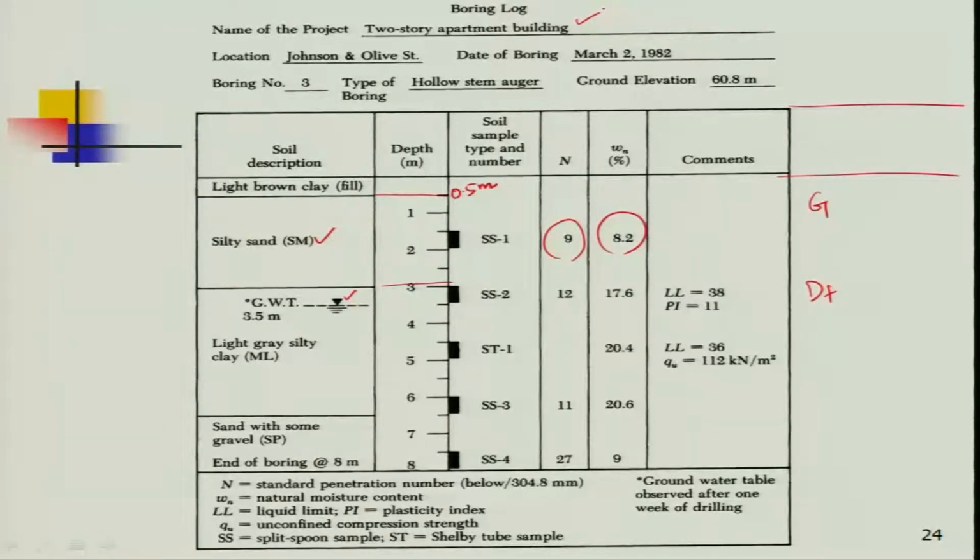Sometimes you go for a 10-story, 15-story, 20-story. In metros, raft foundation has also been used. If it is a very simple 2-story building, you can go for a shallow foundation, either a square or isolated footing or a rectangular footing. Then you have to take a call on what kind of foundation.